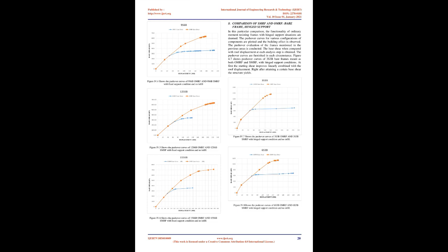Pushover analysis. An examination of the functionality of the created frames is done by conducting nonlinear static, i.e. pushover analysis. The modeling and analysis of the frames is done in the ETABS software. The pushover has a fixed line of action to analyze a structure, where loading on the structure is incrementally increased using a predefined pattern, i.e., inverted triangular or uniform. A nonlinear model is created and the structure is pushed until a collapse mechanism is formed. By increasing the intensity of the load, weak links and failure modes of the structure are located.